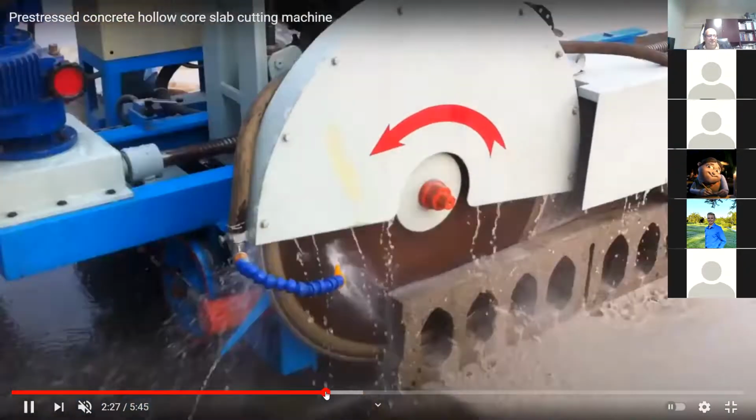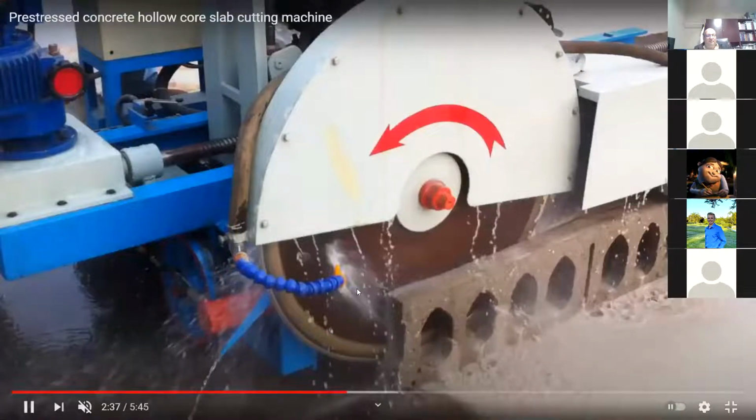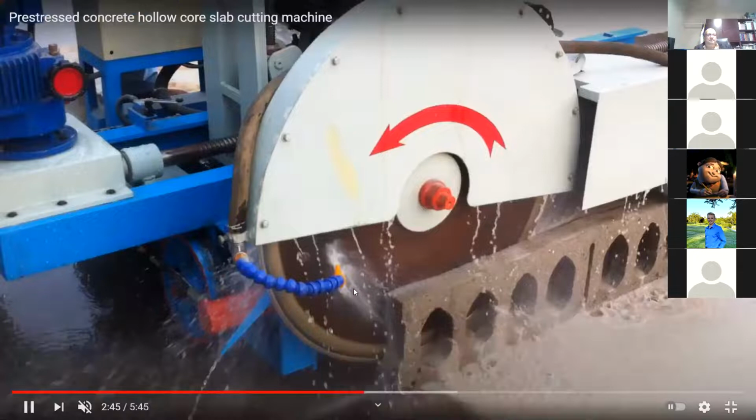So, Professor, they're always on the bottom, right? Yes. Like in the previous design course where we would put rebars on the top, for compression, like at the columns, where the tension switches sides. You don't need to do that for this. For precast members like planks and double Ts, you don't go continuous. It's going to be all simply supported.